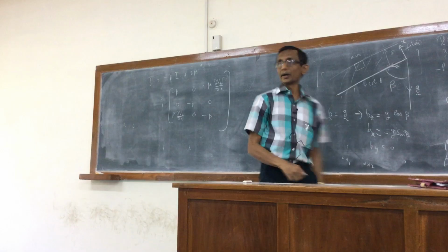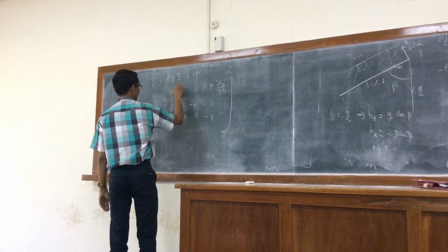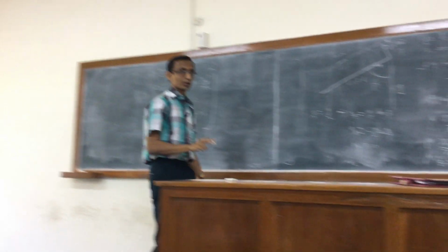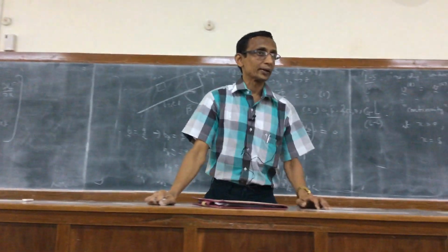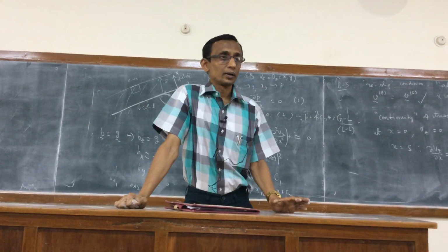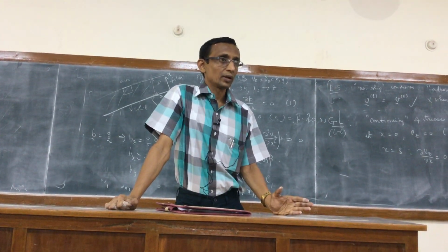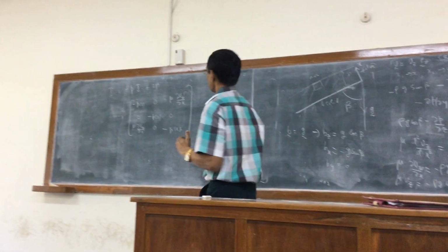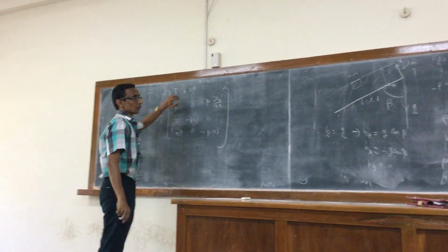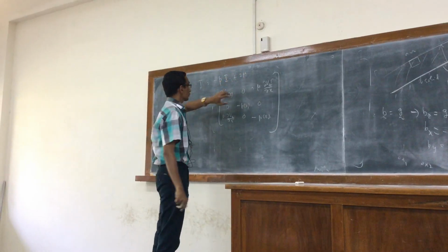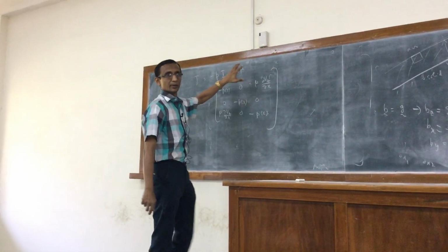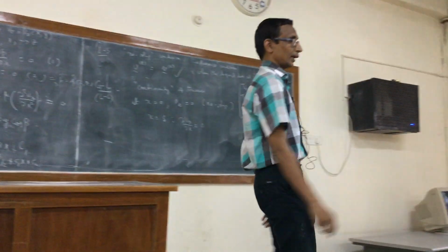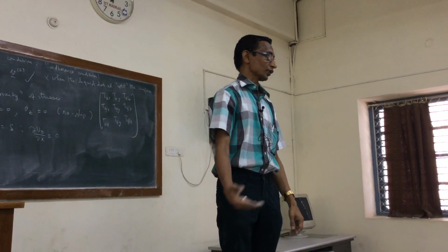Those are the only shear stress components. This is all there is, and if you want, I can write this as everything is a function of x only. There is no other dependence, either y or z, of any of the components. So this is the entire shear stress. So when we say that across the interface there is continuity of stresses, that means all of this at the interface. We know the pressure is the same, right, at atmospheric pressure, so that is continuous.